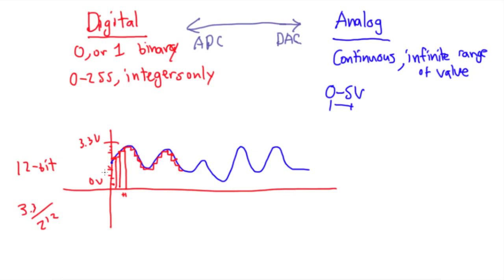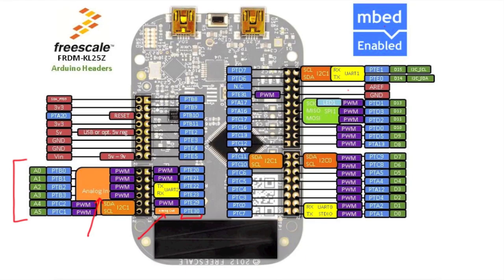You could use a few other techniques to make this a lot smoother, but we're not going to be focusing on that. Instead, we're going to focus on exactly how to use the microcontroller to output this sort of signal. With that, we also need to look at the pinouts of the KL25Z. Right over here is the listing, and you can see the analog inputs.